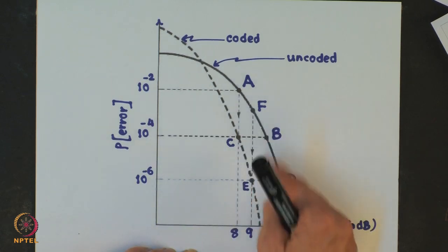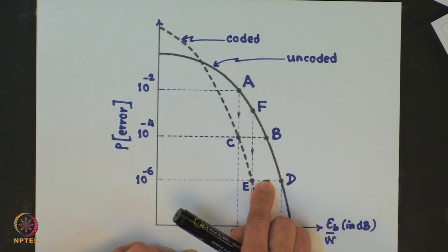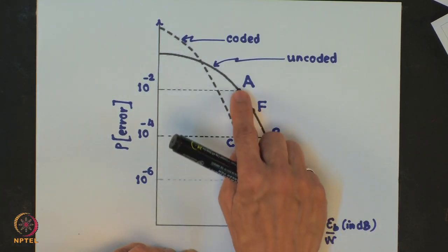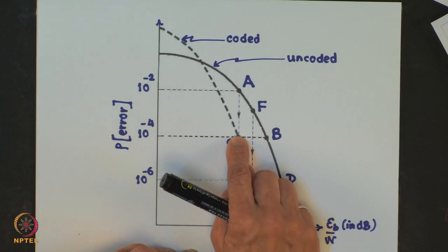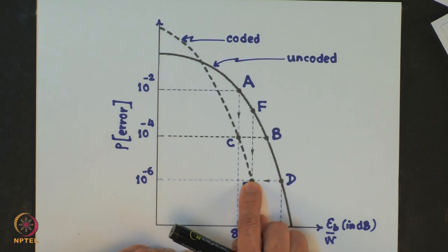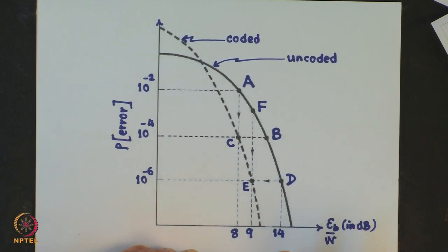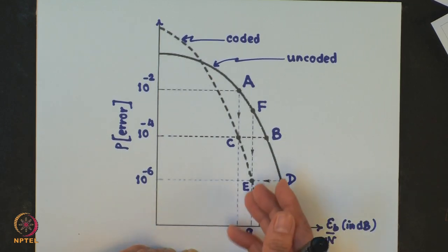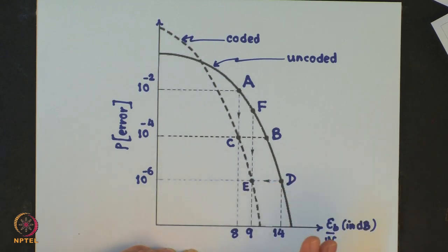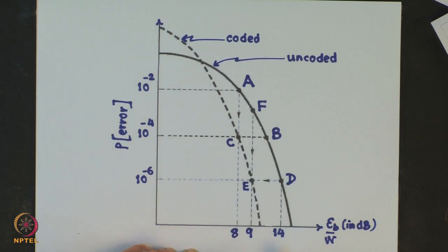Now, for both these cases, it should be remembered that it is possible to obtain improved bit error performance or reduce power by paying the price of delay instead of bandwidth. So, for non-real time systems we can avoid the increase of bandwidth, but then we will have to pay in terms of delay. Okay. Now, let us take another advantage of coding.